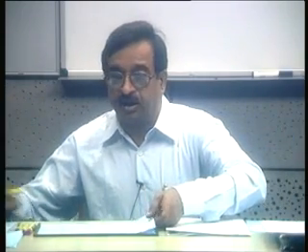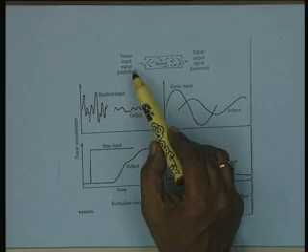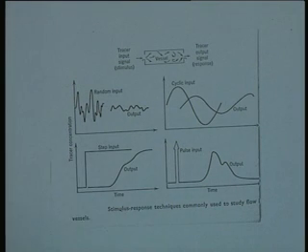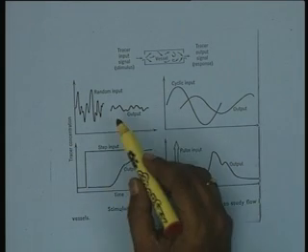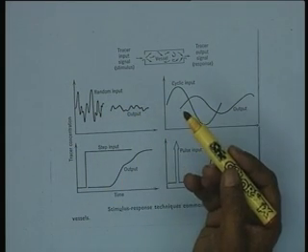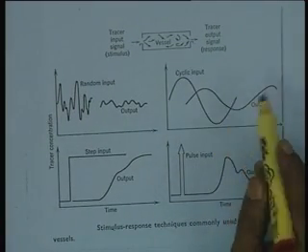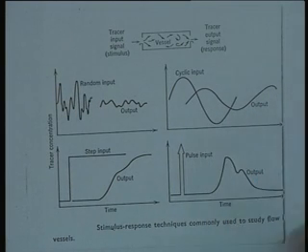If you look at the variety of types of tracer inputs that are inserted into a vessel, let us say consider this is a vessel, we put in a tracer input signal, or what we call a stimulus. It can be a random input. In any fashion you allow some quantity of tracer to be inserted randomly, and of course you notice an output which will also be random depending on the flow profile. Then it can be a cyclic input in the form of a waveform, and then the output will also be some type of cyclic output.